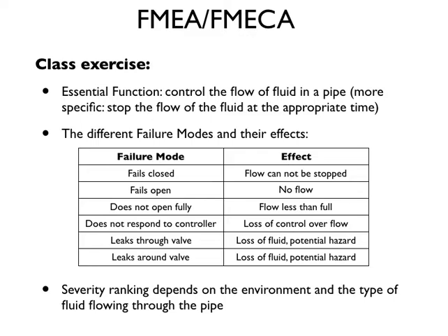And it's important to know that when quantifying the failures later on, for example, the type of fluid will affect the severity of that failure mode. So you can imagine a situation where this exact valve is used in different places around the system, and it would not be true that you could just take an analysis from one portion of the system for this component and copy and paste it to another portion if the working fluid is different. Because again, the severity will change. It may be true that the probability of these failure modes is the same, but the severity of those would be different.